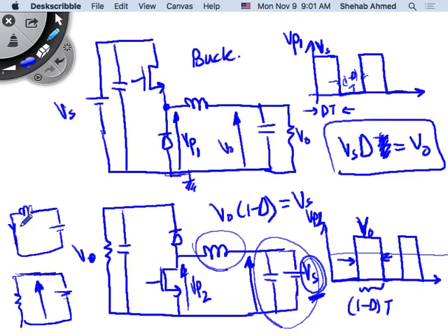It comes from the fact that this is a source with an infinite amount of current, and this is an inductor with a voltage drop across it due to current flowing. You're putting infinite current because of the short circuit that you placed, and you will have an infinite voltage, theoretically speaking, yeah. Right? But does this happen in practice?